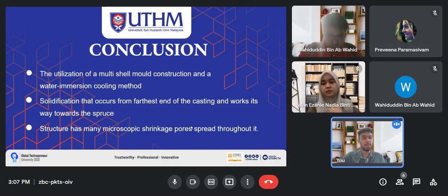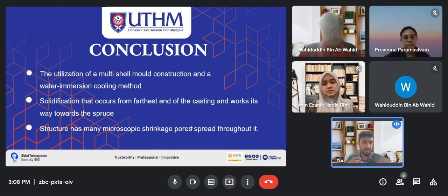Thank you, Praveena. And we are here with the conclusion of the overall article that we have gone through. From the overall research that we have done, we can conclude that the utilization of the multi-shell mold construction and water immersion cooling method to achieve directional solidification from the bottom to the top of a bar is presented in this study. And this is one of the shell mold construction methods that we have used.